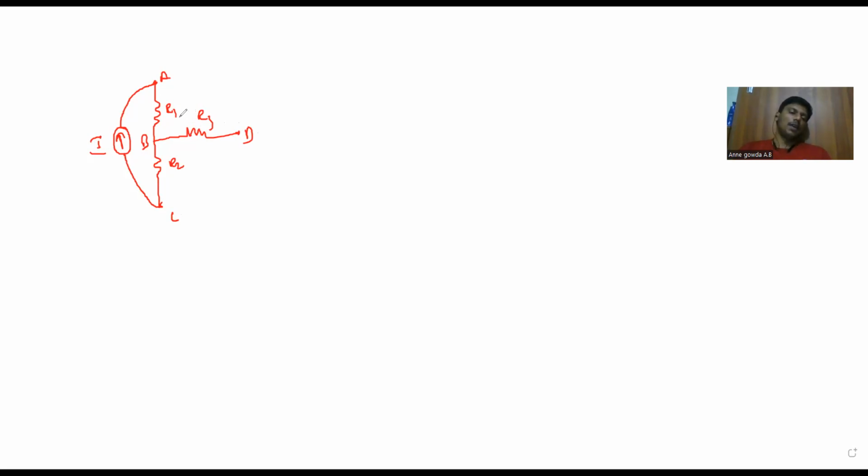So what can be done? See, this current is traveling from node C to node A. So I can make this current source travel from node C to node B first, then from node B to node A. So it is not changing its path. In order to convert this problem so that we can apply the source transformation, I can go with current shifting.